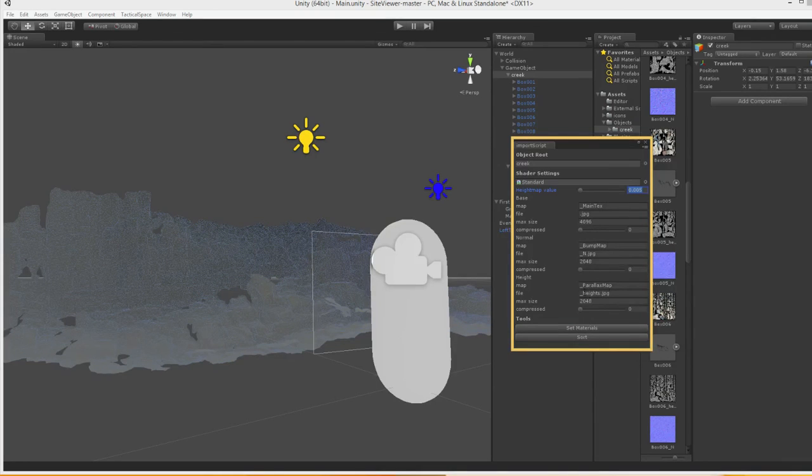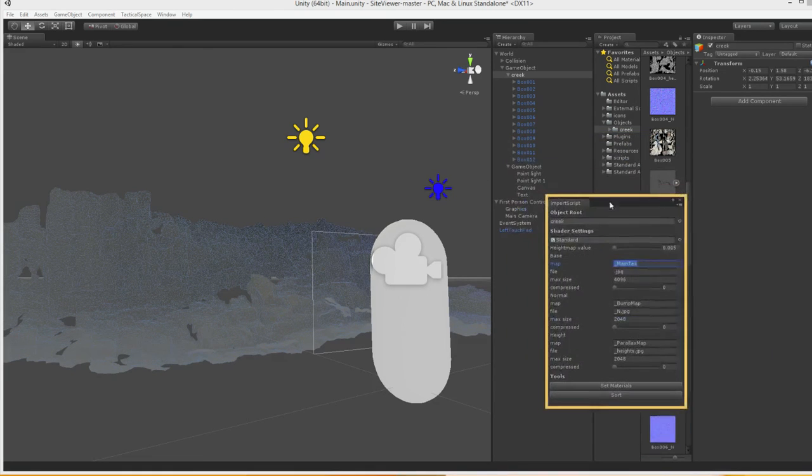All of these names are just for advanced use, if you want to change them. The format is JPEG. This is just saying how to map it from one to the other, like what the name of the texture file to expect, and then to take those texture files and put them into these particular properties of the shader. So you don't need to change anything from these defaults.